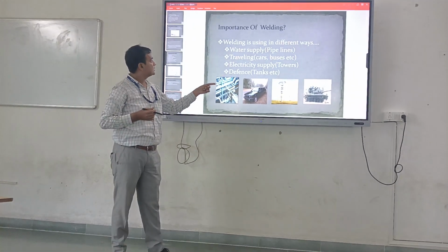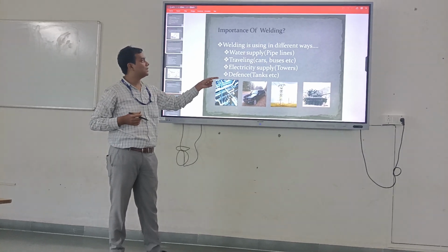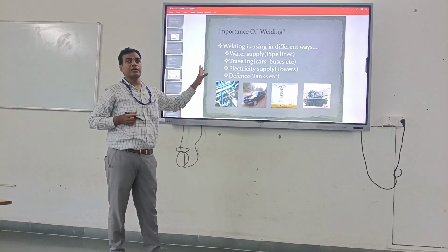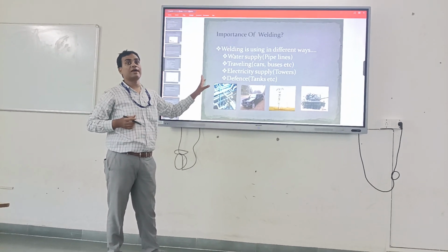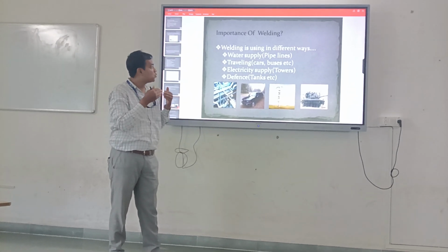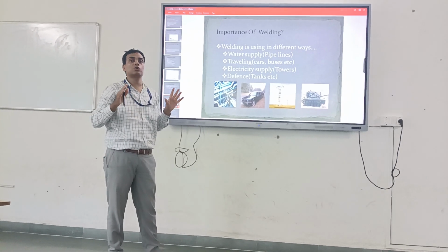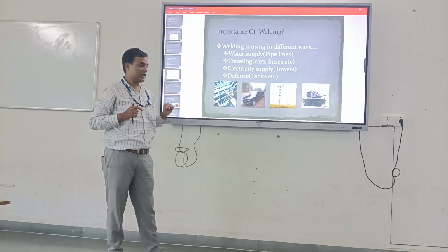So we are using electric arc welding. When I go for gas welding, I cannot use it here because of the high thickness. The workpiece is highly thick here, so we could not use gas welding. So we have to go for electric arc welding.